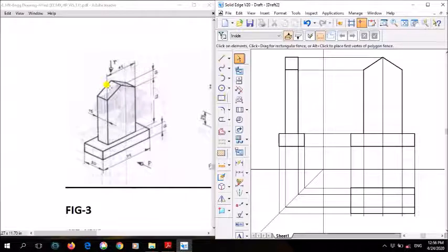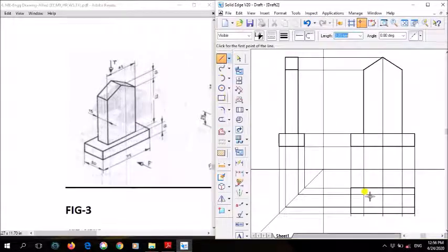This 45 rectangle is divided into two faces here. Again take a line, starting from here at the mid, at the intersection. From here you draw a 45 line. Already this is 45, you just need to draw it using a thick line. And same way downwards, how much is it, 15 mm. Again same way to the right side, left side, 45, again join, completed.